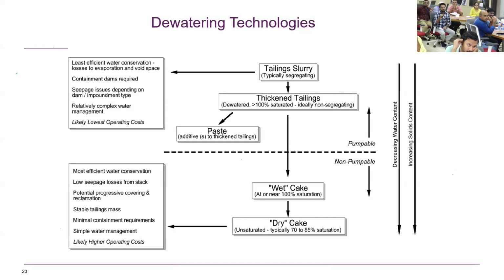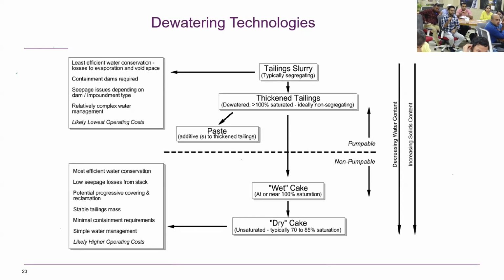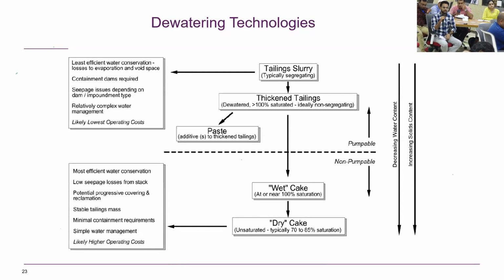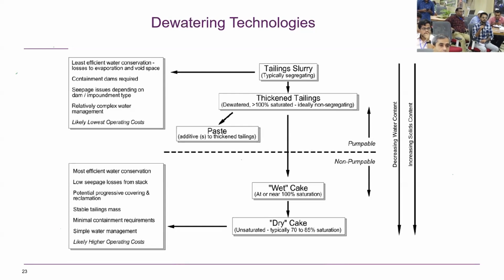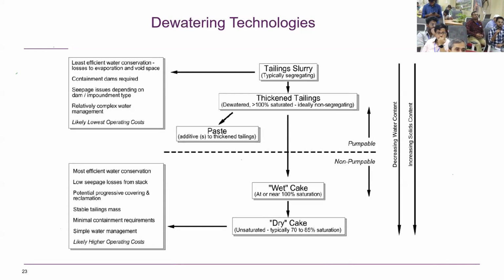I will show how pore pressure rises due to loading and what a safe value is, because it will go on rising. But we want that it should not rise rapidly, because if it rises rapidly, then you cannot control it. You allow it to rise slowly and also stay stable for some period, and that's how we manage it.